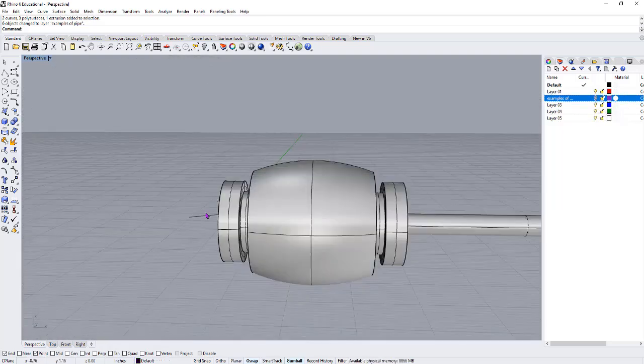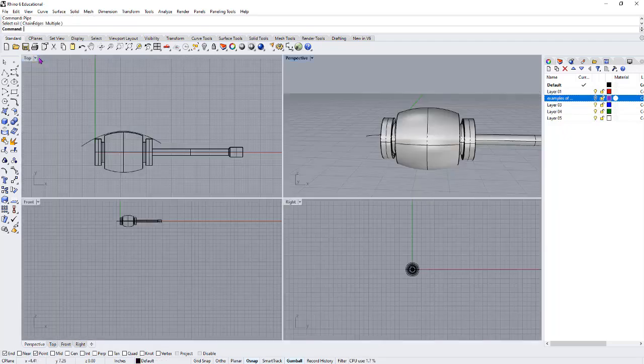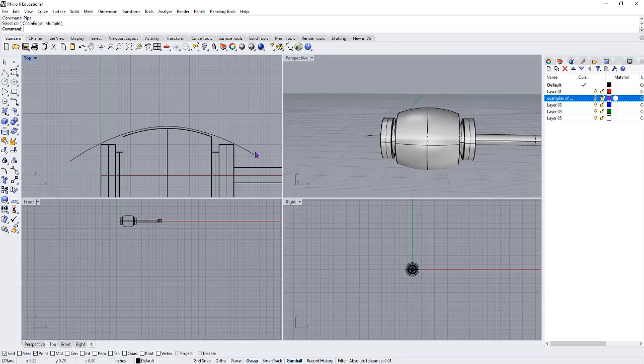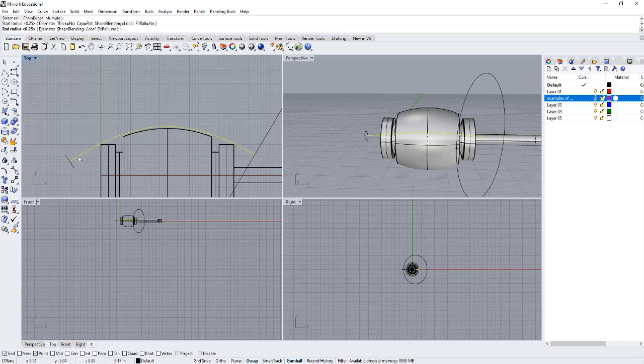Okay, so I created this path already, and I want you to create a pipe along that line that's uniform. So pipe, this object, enter. I'm going to say it's going to be 0.5, so it's 1/2 inch and 1/2 inch at the end.